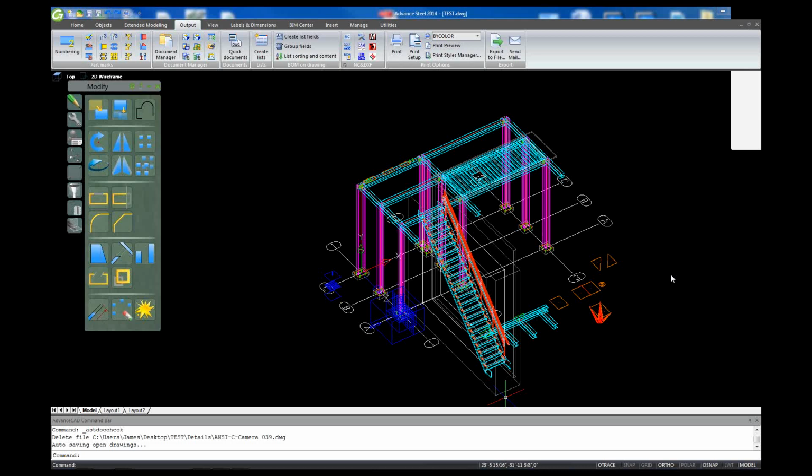Do you have any other questions? So when you create the plan, there's no way at that point, when you create the erection plan, to name it what you want? It's always going to give it the default name the system gives it? Nope. You can rename it, as I have shown. But it's not going to change it in the title block, which is what I'm saying. As I was explaining to James, you have to modify the token. If you modify that token and say drawing name, file name, yes, there is a token on the list named file name. If you change it within the title block, that will work.